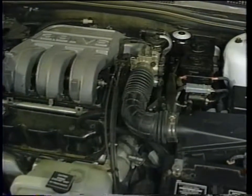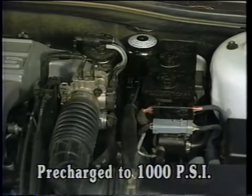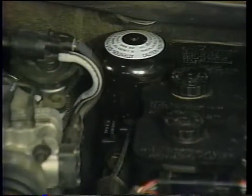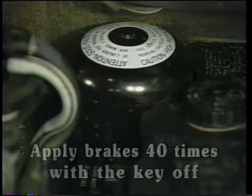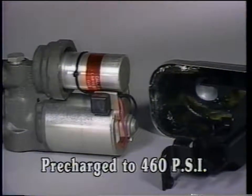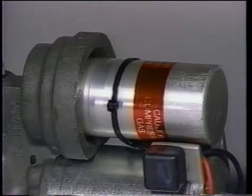Like the Jeep ABS system, it will also have 2 accumulators. The accumulator located on the master booster assembly is pre-charged with nitrogen to 1,000 psi and has a normal operating pressure range of 1,600 to 2,000 psi. The accumulator is a serviceable item, but it must be depressurized prior to removal by applying the brakes 40 times with a key off. A second low-pressure accumulator that's pre-charged to 460 psi and uses a sliding piston rather than a diaphragm is located on the pump motor assembly.